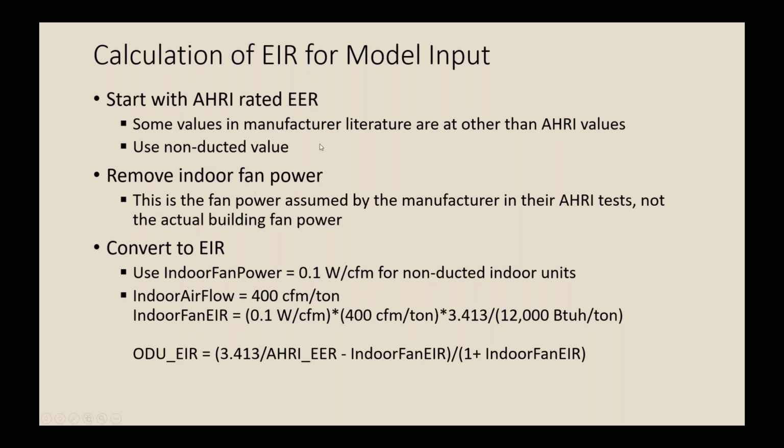Next, AHRI values, again, even though they're being listed for the outdoor unit, the power consumption in the EER includes some assumed value of indoor fan power. So you have to do a calculation to remove the indoor fan power in order to calculate an EIR for the model. None of this is an exact science because of the way the data is published, but I think you can get reasonably close with the approaches that I've described here.